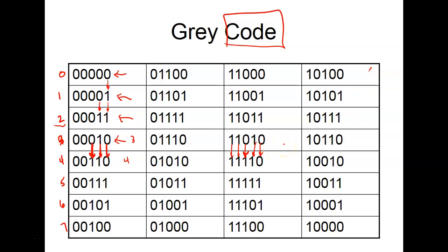So gray code is a code. It's not a binary number system, whether you count up or count down. So let's go this way. How many bits changed? This guy didn't change. This guy didn't change. This guy changed, right? This guy didn't change. This guy didn't change. So on the gray code, no matter which way you count, how many bits change? 1. We could go through this whole chart and we'd always see 1.